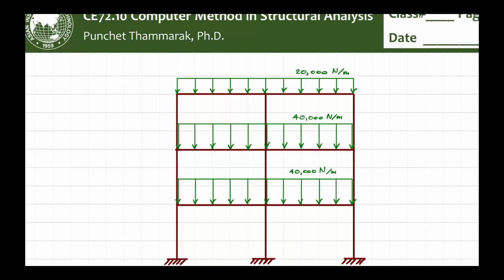Okay, so don't be stingy with the thickness. The load is small, but you don't want the sag. If you have a sag, you have a water pond. If you have a water pond and concrete is porous, it seeps down, it destroys your reinforcement, and so on and so forth. For your house.